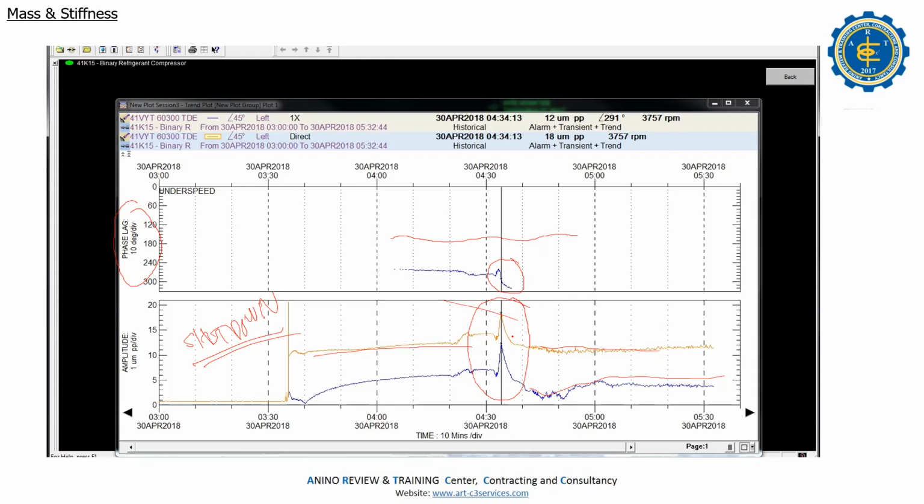It can be, because if your frequency is different and your amplitudes are varying. That's why you have to firm your answer. If you have high vibration and the phase angle changes, yeah, 180 degrees, then that is 100% critical speed.